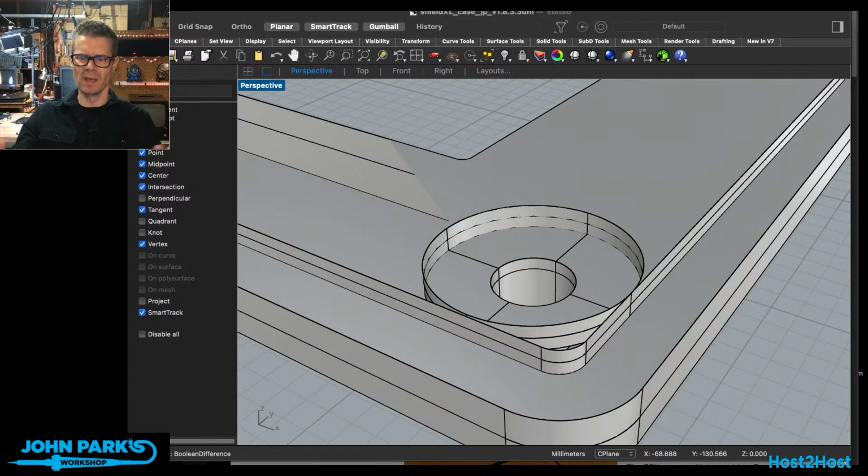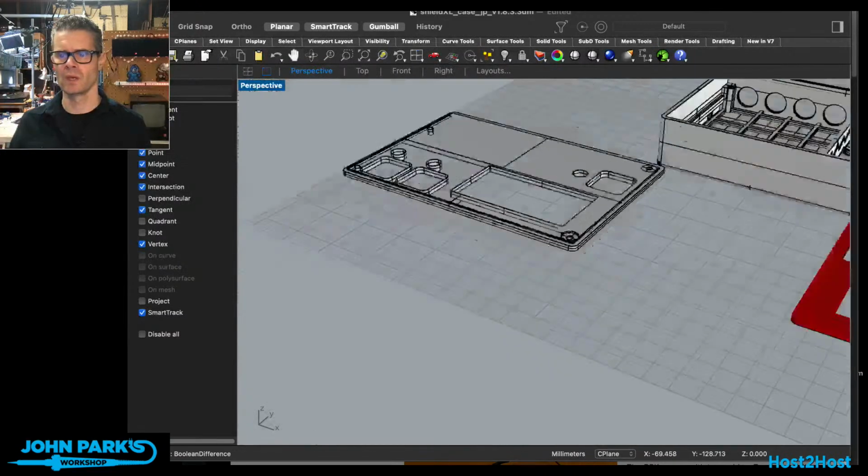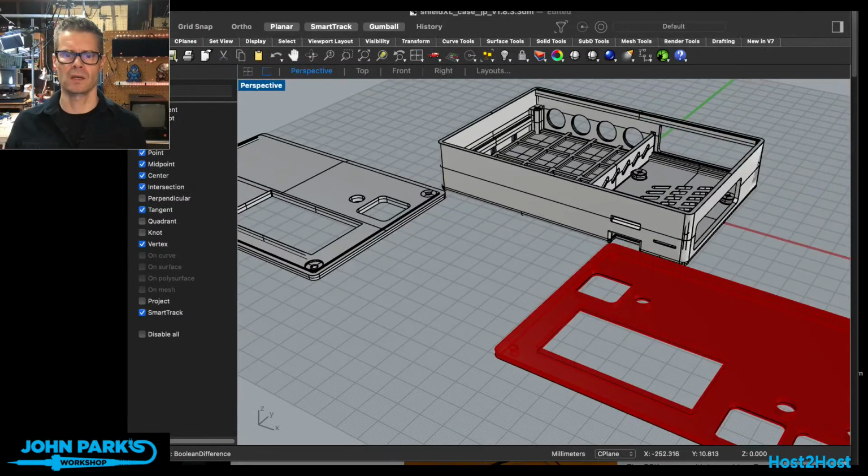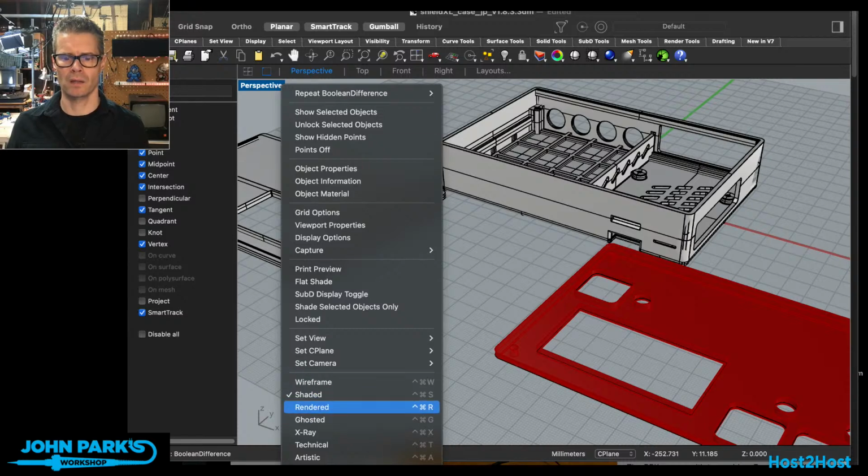But you can see it right there, that little divot there, that's what's going to give me some clearance for setting the lid all the way flush, but allowing that just millimeter that I needed of the hex nut. And we could make a proper hex pattern, but then it has to be aligned. So just a circle bigger than that hex nut would be fine. And I measured that earlier, and I think this is a 6 millimeter circle that clears it, so that should work.